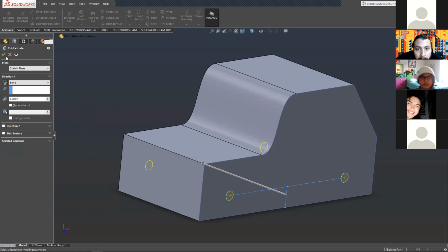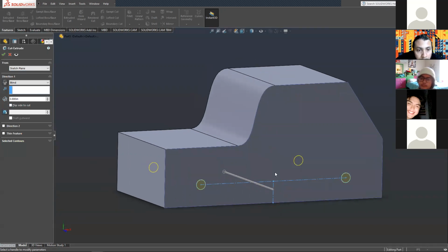The sketch has both open and closed contours. Pick a sketch region to define an open and closed contour. Oh, so is one of your lines here not a construction line? Is it like a regular line? Yeah. So change that. You can just select a line, and over here on the left side it will say properties, and you can just click for construction. It's a little checkbox. So that's another thing to keep in mind when you're doing these setup drawings. Make sure they're construction lines, they're center lines.